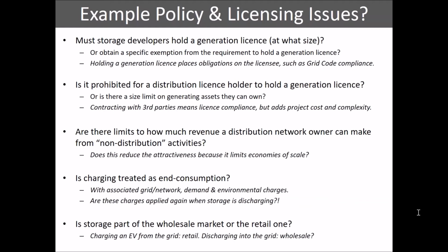There are also rules about how people get paid or pay for using the network. So again, this is a common one as well, or has been highlighted as a potential problem, is double charging. So if you're attached to the distribution network, if you're a big energy user, you get charged for usage, not just usage in terms of the amount of energy used, but also things like demand charges, capacity charges, and so on. So if you're a battery and you're seen as a source of demand, which we said it can be, then you could get charged those things when you charge your battery. But also generators get charged for grid usage as well. So when you're discharging your battery, you get charged again. So there's issues like that.